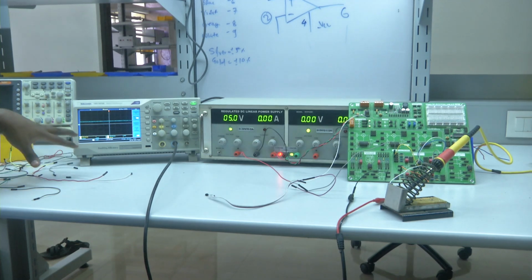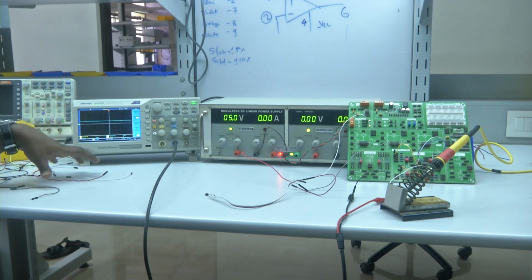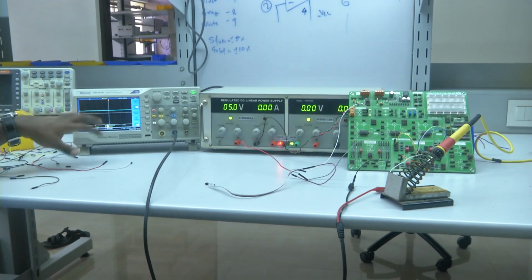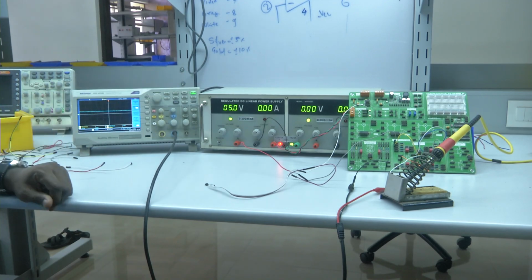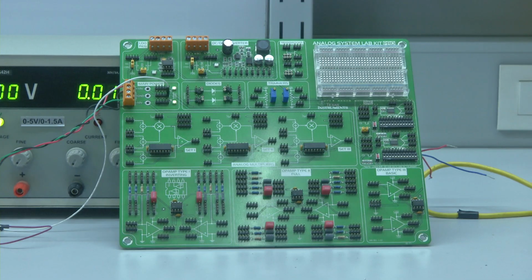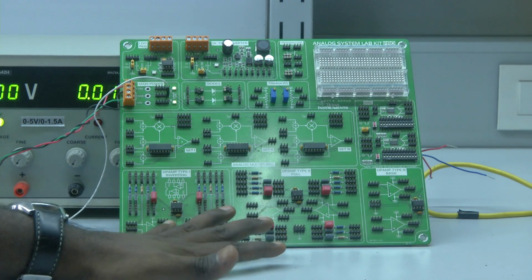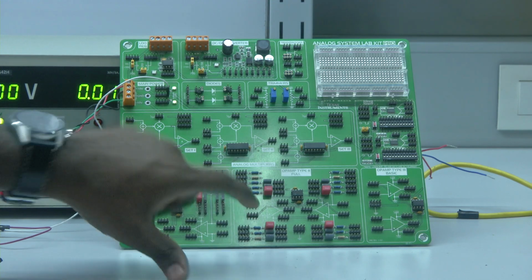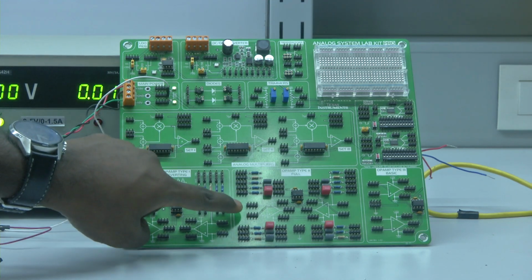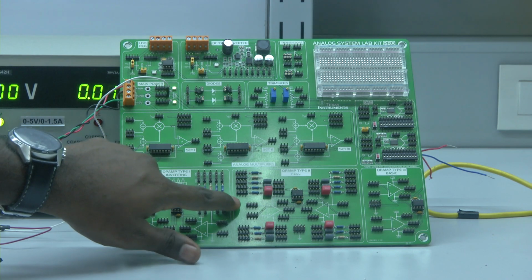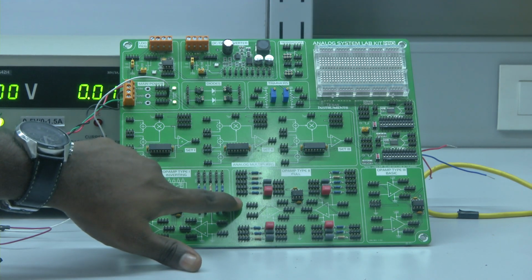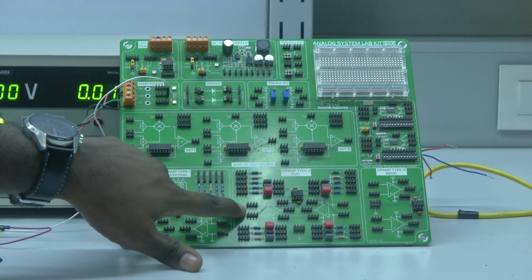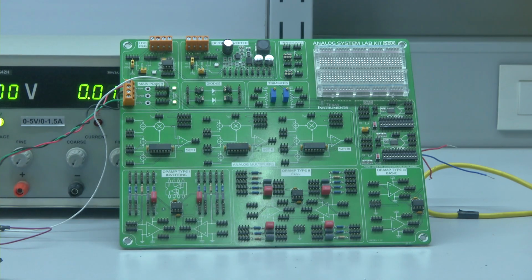Now we will try to realize the same circuit the same way, whatever we have done for the inverting amplifier configuration, we will also try to implement the same by using non-inverting amplifier configuration too. Now see how we can implement the non-inverting amplifier configuration at this stage. In case of a non-inverting amplifier configuration, we can use only one operational amplifier where the input should be connected to the positive terminal, and the feedback resistance as well as the input resistance, the other end of the input resistance should be connected to the ground.